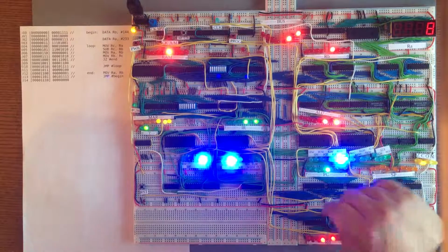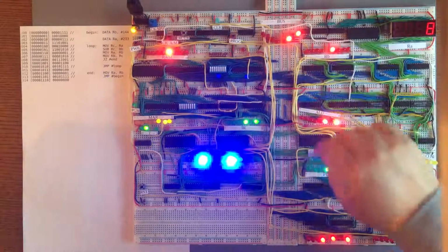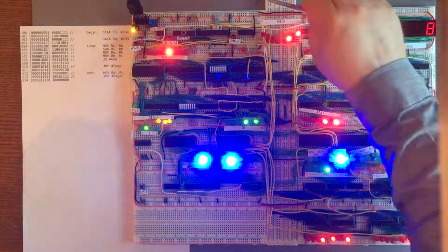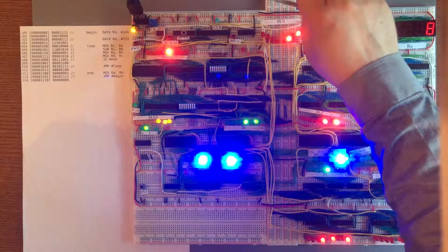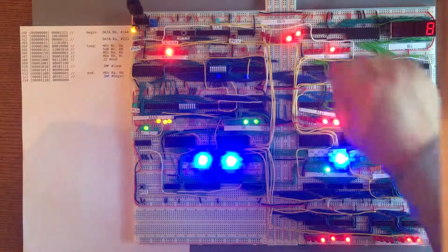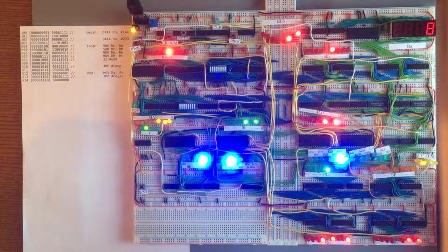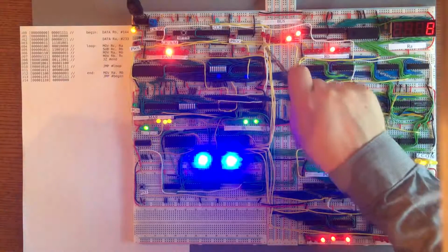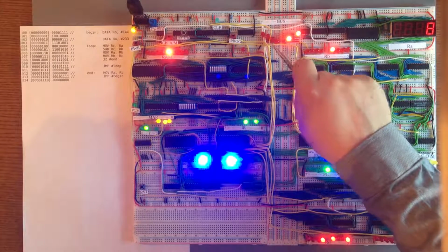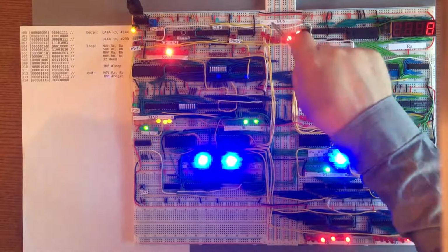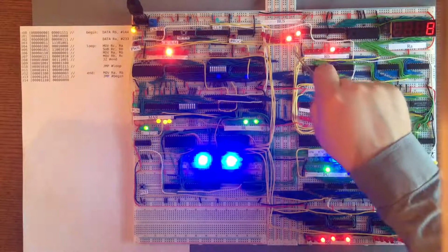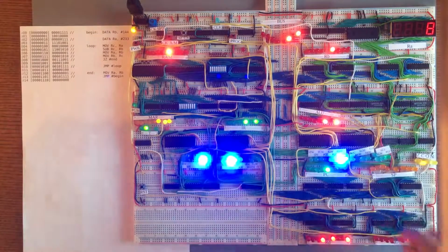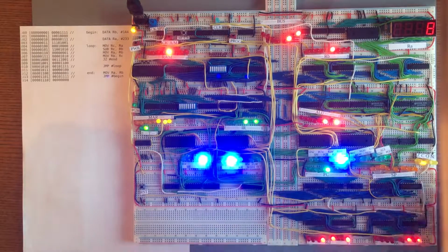And the way that works is through a bus, and here is my bus. And so the bus is just this, basically it's a collection of 8 wires. It's nothing more than that. And so this C register at the moment is outputting its contents of 5 onto the bus. And in fact you can see it here because I've installed some LEDs so I can see exactly what the values are on this bus. And at this moment it's 5, which is what the C register is putting out onto the bus.